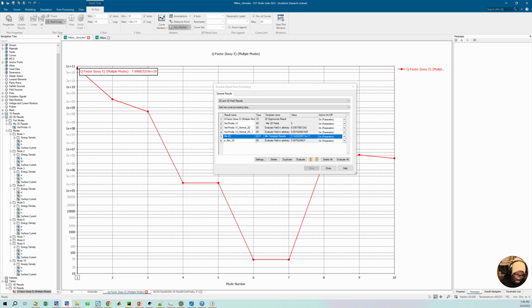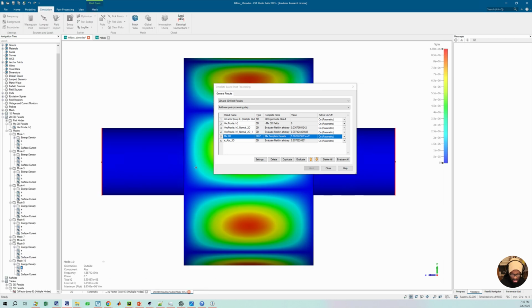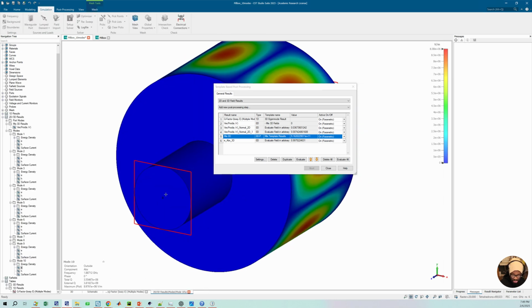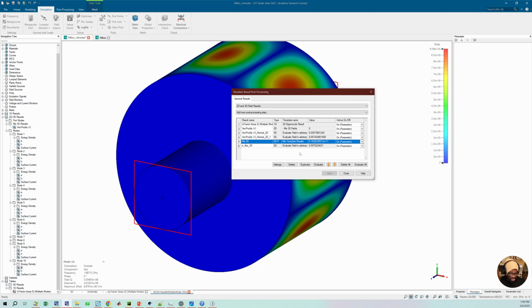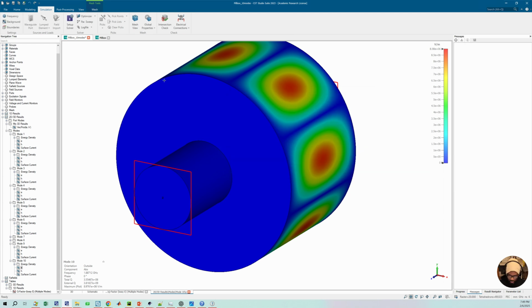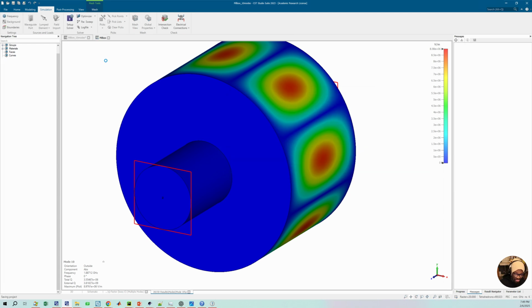And you would also notice the same if you calculate for mode 2, mode 3, and mode 10, and some other modes that are strongly trapped. What I mean by strongly trapped is the mode does not propagate into the beam pipe, or it propagates really weakly into the beam pipe, which means that the external quality factor is really high. For very high external quality factors, it's very sensitive to the mesh resolution, and you generally do not have the same results. And not just the mesh, but also many other things which I do not know. And why do I say this? I ran another simulation.